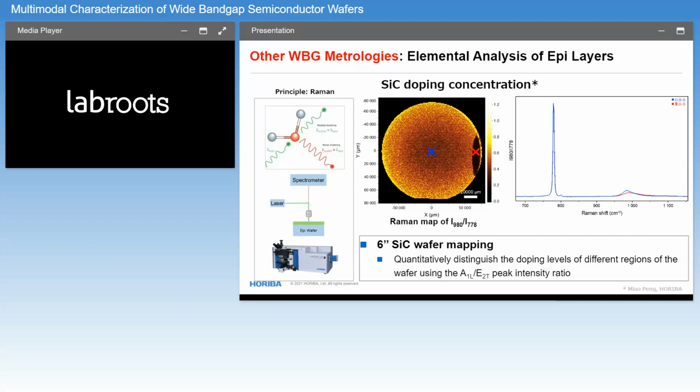For that there are other techniques being used today, like mercury touch probe techniques, which is a contact technique, by the way. We can do such things these days using Raman spectroscopy, which is non-contact, and of course less prone to introducing foreign materials on the wafer because of contact measurement. In this case, we're looking at two well-known peaks, and the ratioing of those peaks as methods have been devised to correlate that measurement to doping concentration.